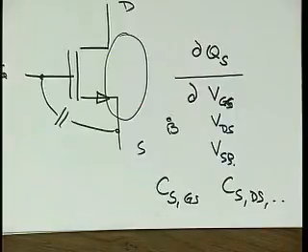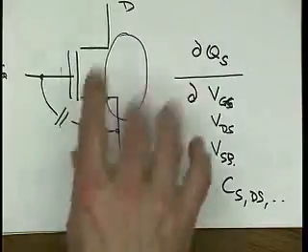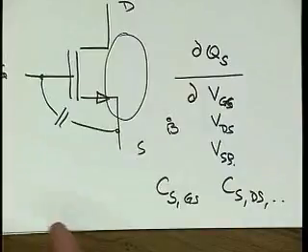The total charge in our device better sums to 0, and I also get 4 voltages between all the terminals, bulk terminal and the 3 other ones, of which 3 are independent. And then consequently I have a matrix of 3 by 3 or 9 such derivatives. And SPICE actually does that. SPICE actually calculates those 9 derivatives.